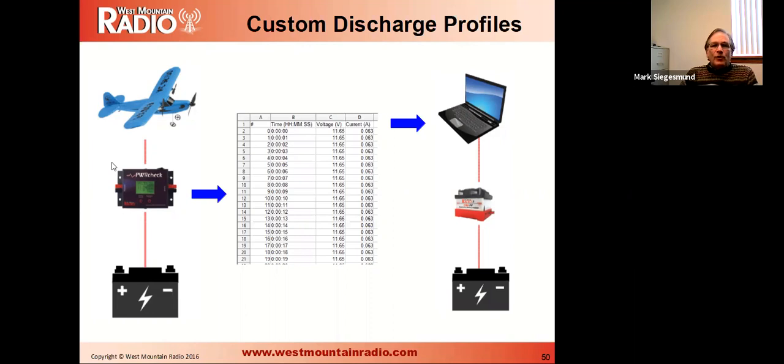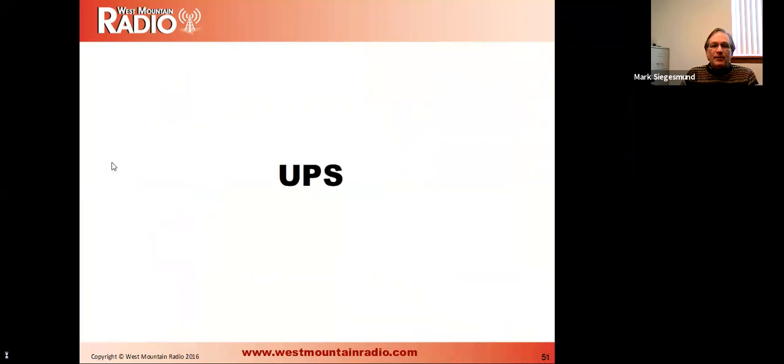So you can do exactly that same discharge as flying, for example, right on the bench. So you then have the opportunity to try different batteries and say which batteries work better for the particular application that I'm going to be using. Anyway, CBA is a lot of fun. So if you're doing anything battery-wise, that might be a nice tool to pick up.